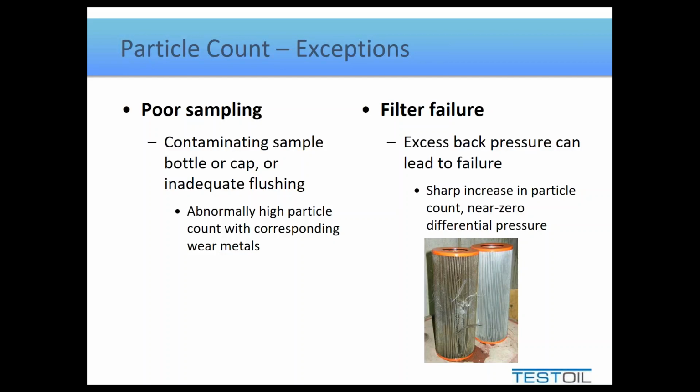And the presumption is that every time there is a filter change, the particle count should go down. What I'd like to suggest to you, though, and this is just from my experience, is that in fact changing the filter sometimes causes the particle count to go up even further. And what I'm not suggesting, because this is commonly said but is not accurate, is that a new filter is less efficient than a used filter, and therefore this is expected. I don't want to endorse that statement.